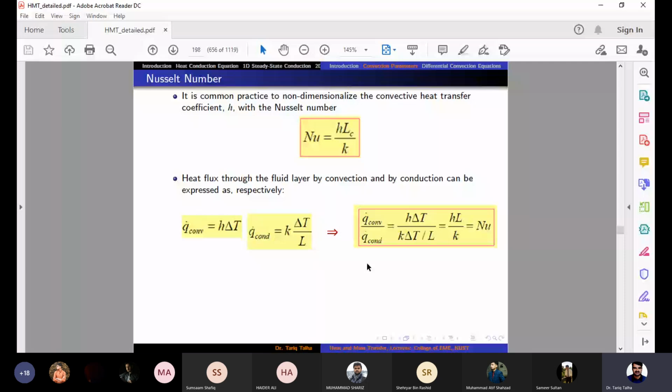most light molecules, because they are the most heated molecules. Now they cannot go downwards, right? They would stay upwards. The first layer would stay at the same top position, because that is the most heated, most hot molecules, and they cannot go above, because above we have some restriction. So they would only transfer heat to the bottom layer by conduction. So there would not be any fluid motion due to that buoyancy effect. Is that clear?